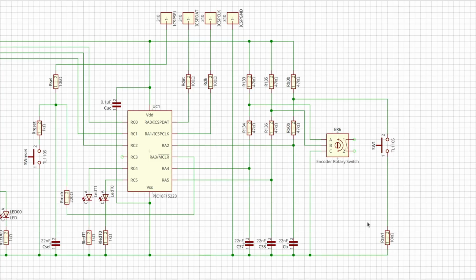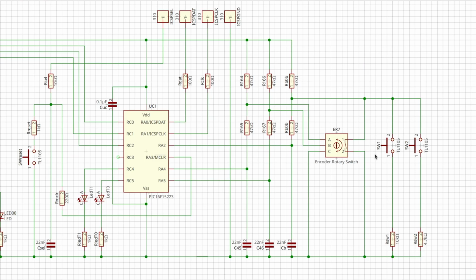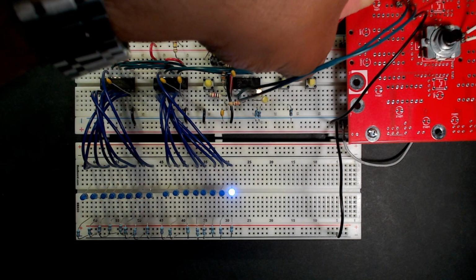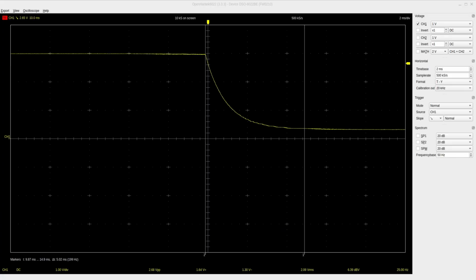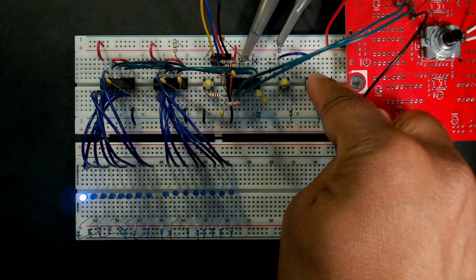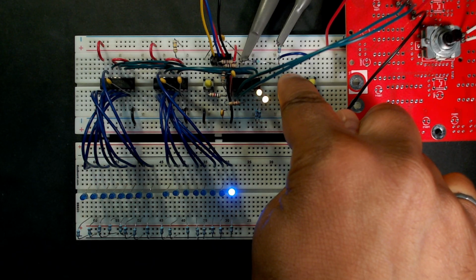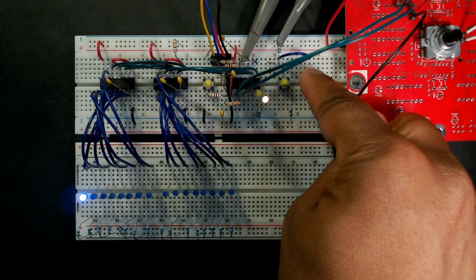So now for fun, we can try changing this resistor to something else, but instead of doing that, why don't we add a second switch with a different resistor? In this case, it'll be a 4.7 kilo ohm resistor. And take a look at the signal as we press it. Oh, look at that. With the 4.7 kilo ohm resistor, it's settling at around 330 millivolts. And yet our digital microcontroller still can't tell the difference between these two buttons.